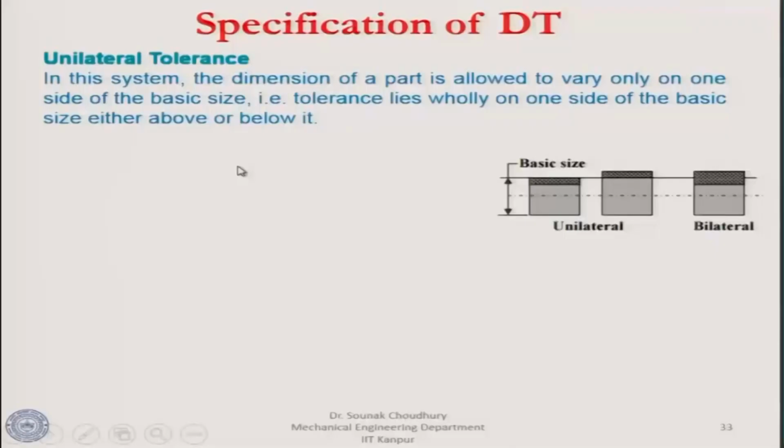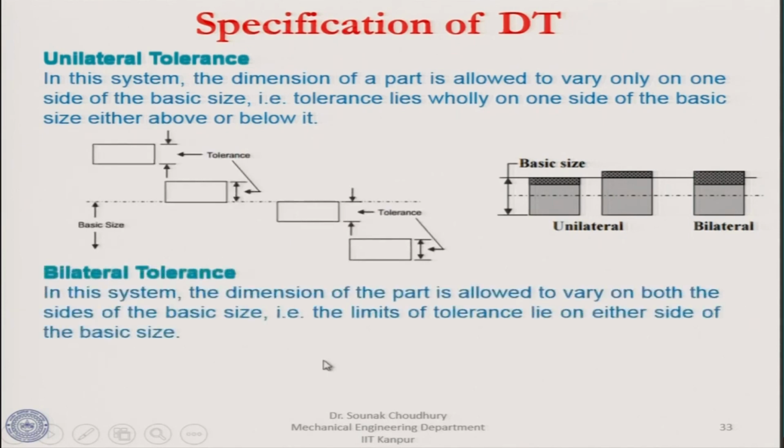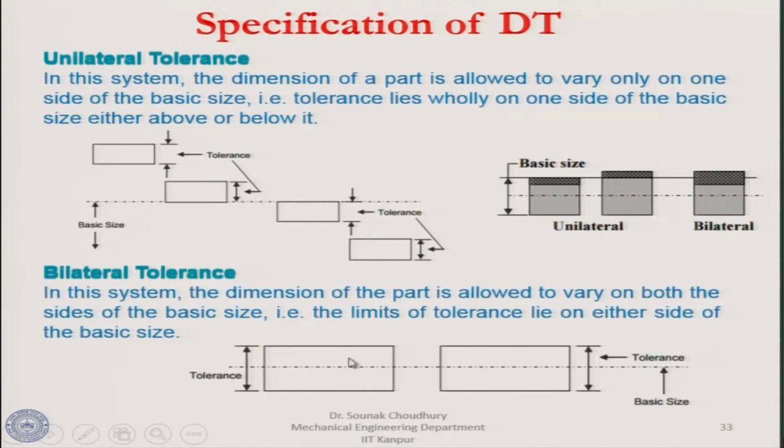I will show you what are those groups of tolerances, depending on which it is given that two mating surfaces are tightly fit with each other, or not so tightly fitting. These are given as unilateral tolerance, on one side, or bilateral, where tolerance is given from both sides.